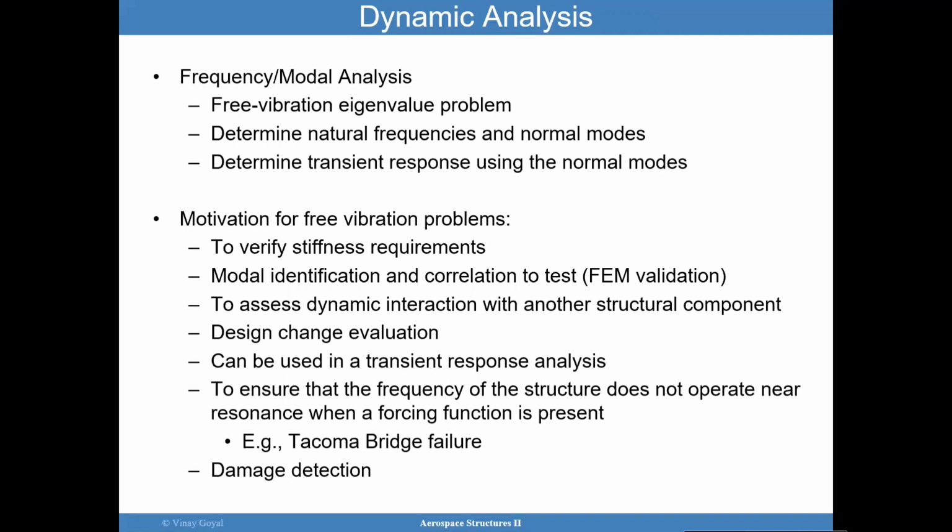The motivation for free vibration problems, however, can be used for many other things. You can verify stiffness requirements. You can validate finite element models. I'll discuss that later in a future lecture. You can assess the dynamic interaction too. You can look at the changes that occurred to the system due to a design change, so you can evaluate design changes. You can actually even use it as structural health monitoring.